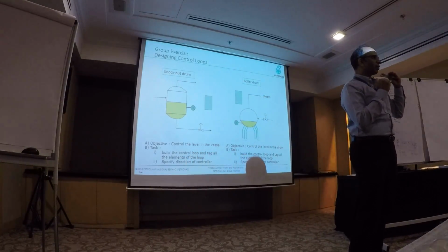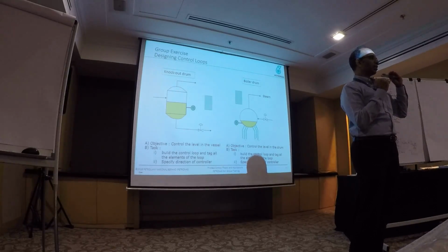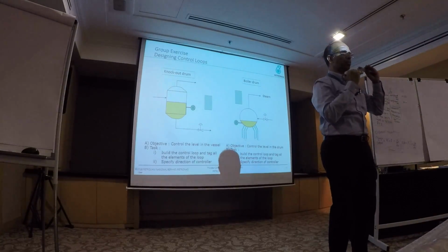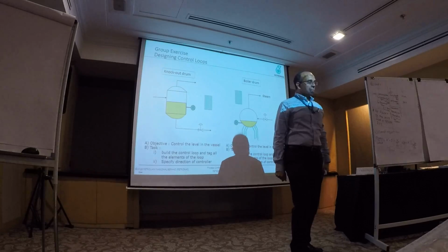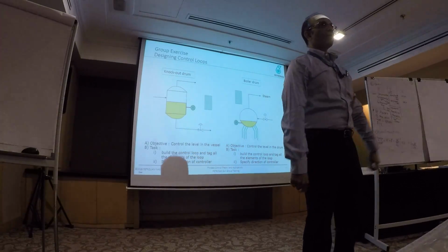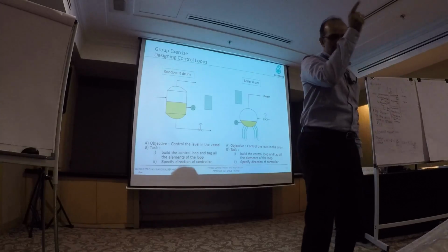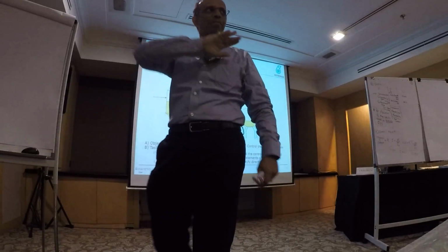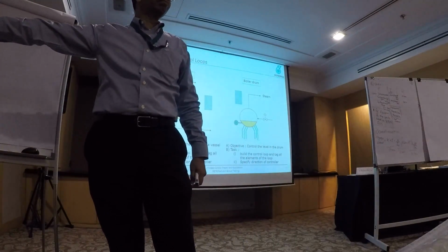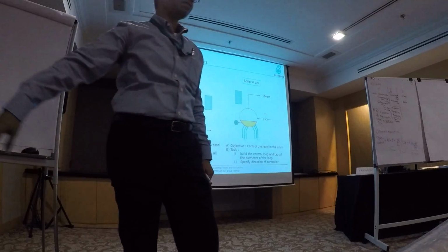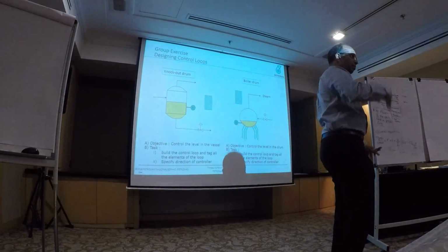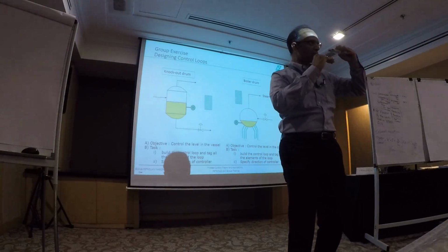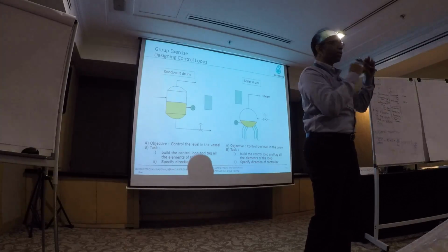But the block is running at 1 second intervals. So the block processes the 10%, it sends an output change of 10%, then it comes back again after 1 second. Okay, what's the error? 10%, oh my god, change the output by another 10%. What happens? In 5 seconds, you've already hit 0 or 100%. So the problem with discrete systems that process every second is that if it continuously sees an error, it will change its output.